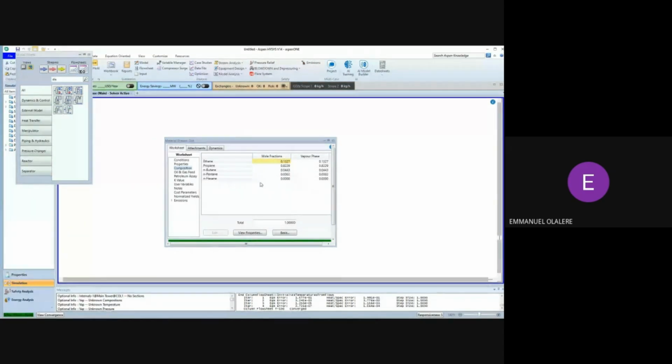Normally, we expect ethane to have higher composition. But if you compare the composition of ethane and propane entering the process, the composition of ethane entering is 3%, while for propane it is 20%. Since they don't have equal composition, it might be expected that we have more propane in the vapor phase, which is reasonable because the amount of propane we have is about 7 times the amount of ethane we have. That is why the composition of propane, even though it should not be higher, is higher than ethane, because we have more propane in our stream. So these are the compositions and everything.